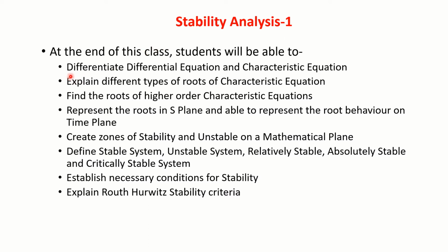So in this session, we'll differentiate differential equation and characteristic equation. We'll explain different types of roots of characteristic equation and find the roots of higher order characteristic equations, represent the roots in S-plane and represent the root behavior on time plane, meaning the system behavior on time plane, then create zones of stability and unstable on a mathematical plane.